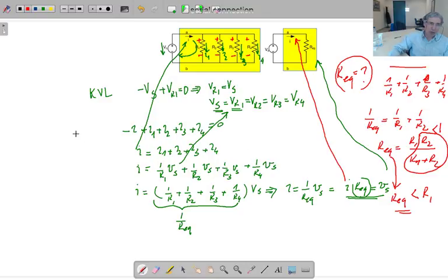One of them is the analysis. It is useful. Why is that? Because in the analysis in general we are writing Kirchhoff voltage law equations, NE minus ND plus one of them, and then we are writing Kirchhoff current law equations, ND minus one of them, the independent ones, and NE element definition relations, all together two NE unknowns, two NE equations.